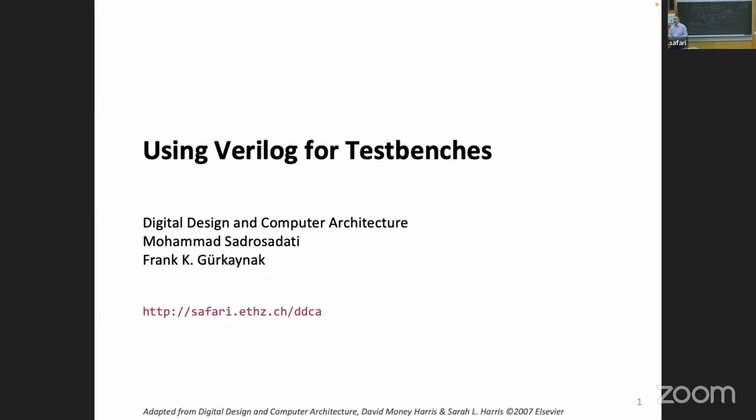can be and is usually implemented as a Verilog file that we call the test bench. Now, it is not strictly necessary that all parts of the test bench are implemented in Verilog. It is also possible that parts of the stimuli generation and golden model are also done in Verilog. Happens.